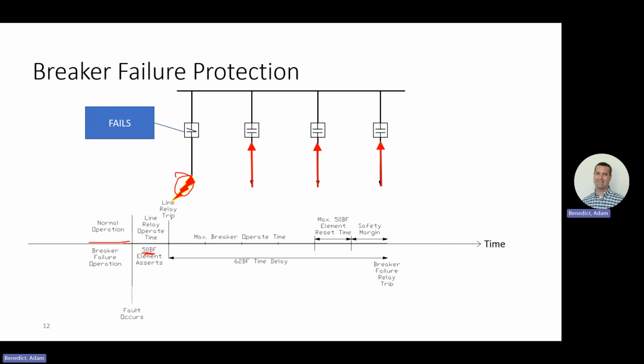At that point, there's a little bit of time between detect and trip, right? There's always, nothing happens truly instantaneously. You're going to detect this in a few cycles, and then you're going to try and trip it within a couple cycles, 3 cycles, right? So this will probably happen within, say, 6 cycles. At that point, you're going to try and trip this breaker. At that point, your line will do a BFI, breaker failure initiate.